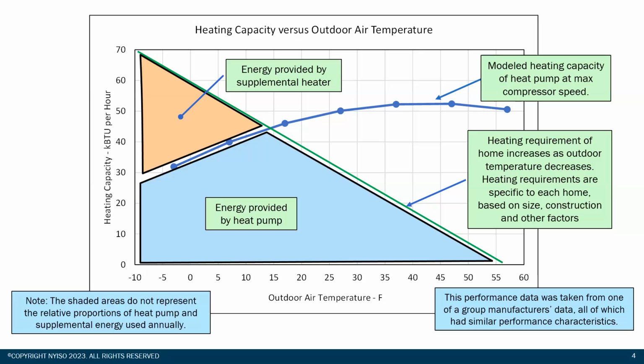And the heat pump performance, a 5-ton heat pump, is going to provide maybe 50,000 BTUs per hour when it's warm, and that gradually decreases due to essentially the laws of thermodynamics. You can bend that a little bit, but unless you have a ground source heat pump, which is flat year round with the temperatures, this is the performance one way or another for an air source heat pump.